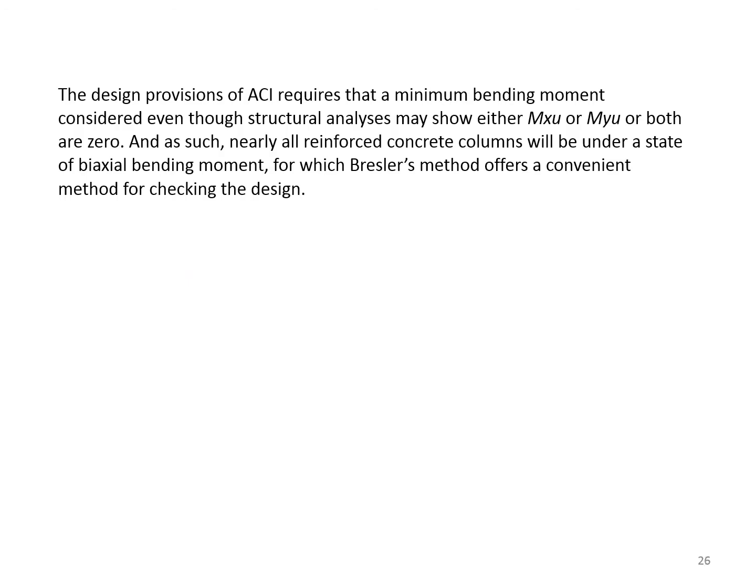The design provisions of ACI require that a minimum bending moment be considered, even though a structural analysis may show that either Mxu or Myu or both are equal to 0. And as such, nearly all reinforced concrete columns will be under a state of biaxial bending moment, for which Bresler's method offers a convenient method for checking the design.